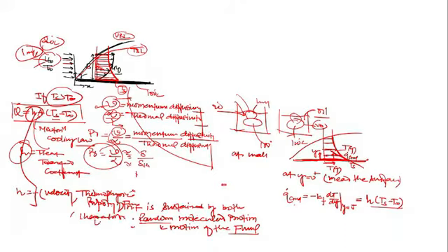I am talking about the case when there is no phase change. Only convective heat transfer that does not involve any phase change. Two types of convection problem are there: one involving phase change and one without phase change. So when I am talking about convective heat transfer without phase change, the heat transfer coefficient depends upon the velocity of the fluid, the thermophysical properties, and also on the characteristic length of the object.